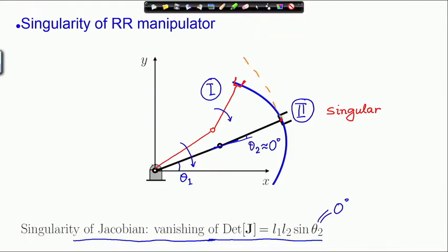So, this is roughly the boundary of the workspace, which we have discussed before. This point of the path lies on the boundary of the workspace. Therefore, the manipulator goes to a singular configuration. At this configuration, if you want to proceed further on the path, which again comes into the workspace, as you can see, it touches the workspace boundary and then again comes inward into the workspace. So, therefore, it can be continued.